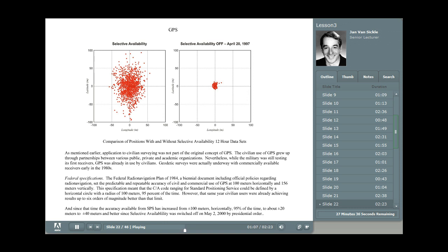And obviously, as you know, if the clocks or the oscillators in the satellites are tweaked, are moved, and don't keep a steady standard, then the positioning derived from them would suffer. And so using selective availability for quite a long period of time in the early years of GPS, it was possible to degrade intentionally the accuracy available to the civilian C/A code users to the 100-meter specification.